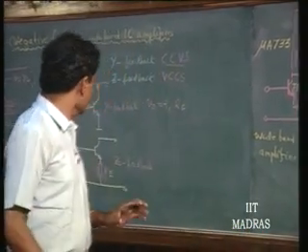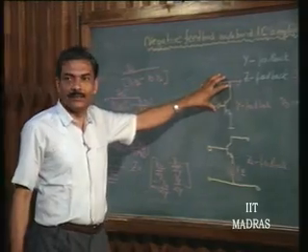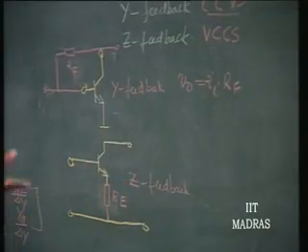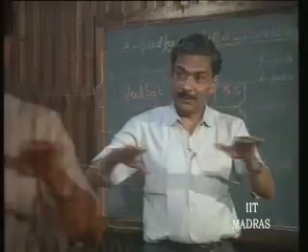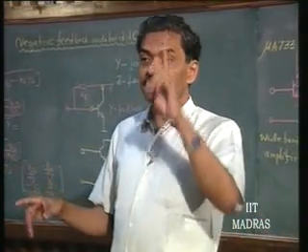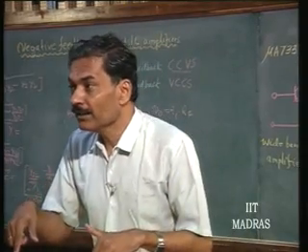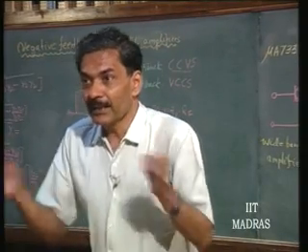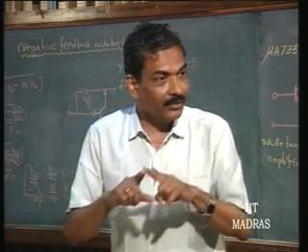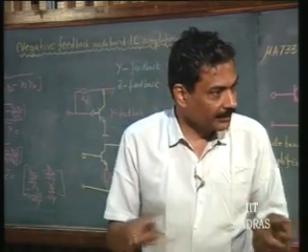So that kind of stage is only this for Y feedback and this for Z feedback, and therefore the other two do not exist. Please try to do this: H and G feedback using a single stage cannot result in negative feedback, they will always result in positive feedback. So H and G feedback do not exist.